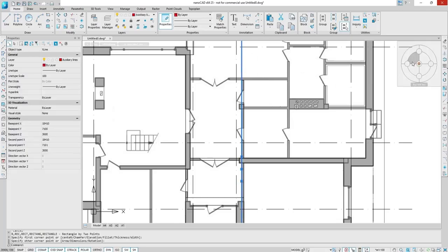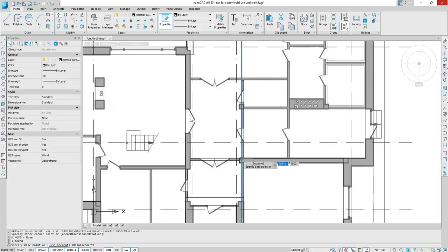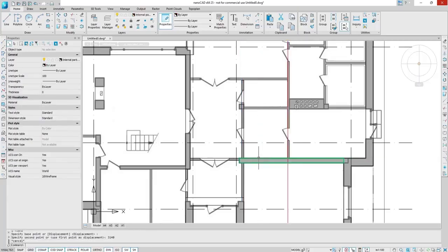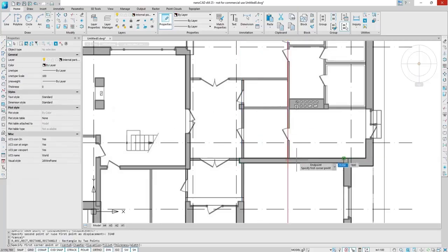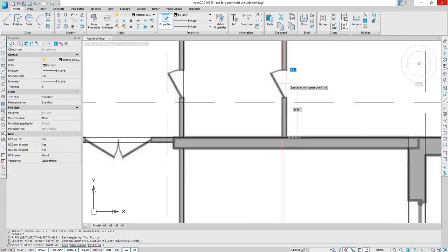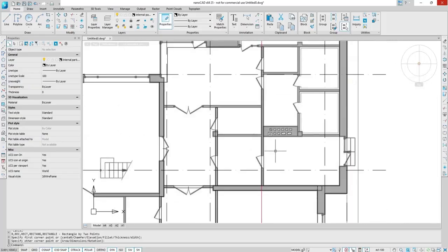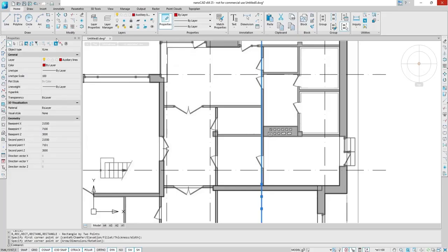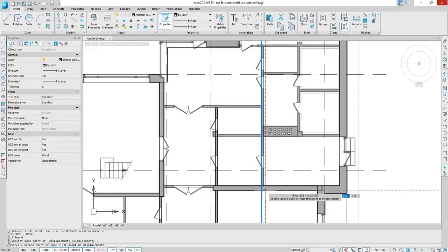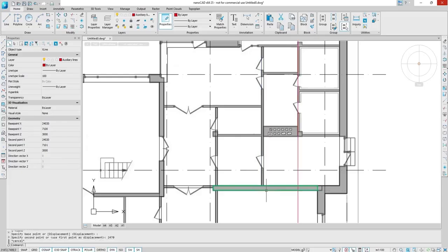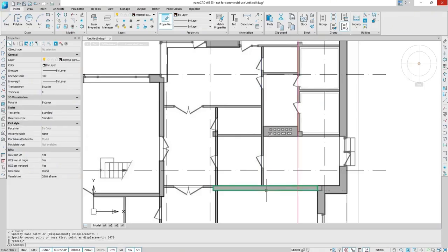Seventh partition. Move the straight line to the right by a distance of 3,140. Set the value from the keyboard. We draw a rectangle from left to right up 140, 9,000. Move the straight line to the right by a distance of 2,470. The same can be done with horizontal guidelines.